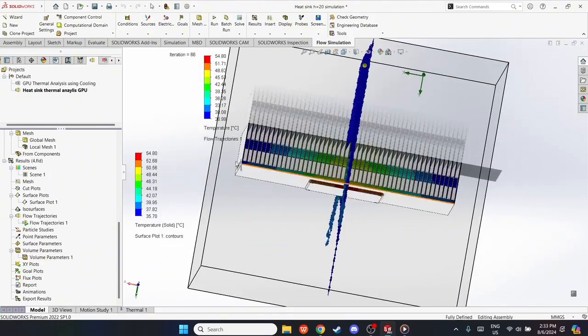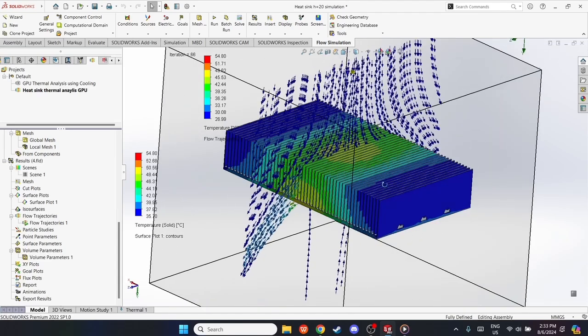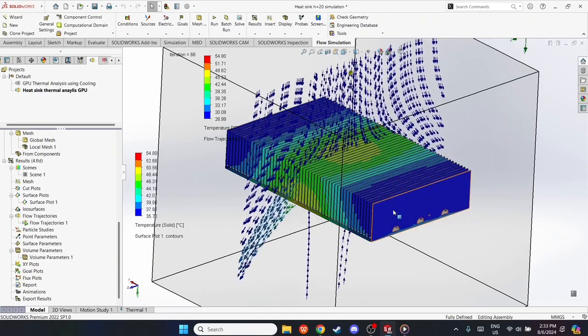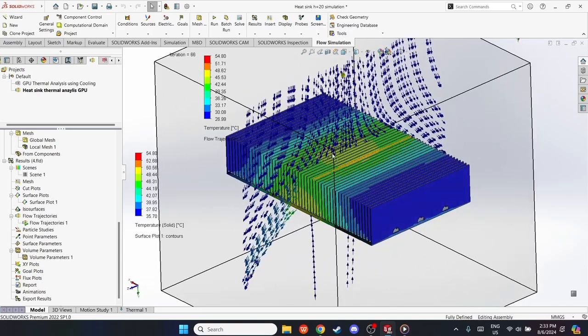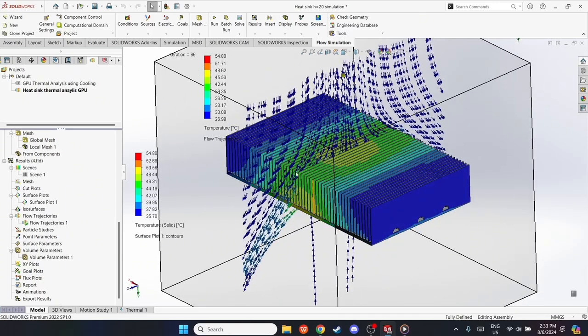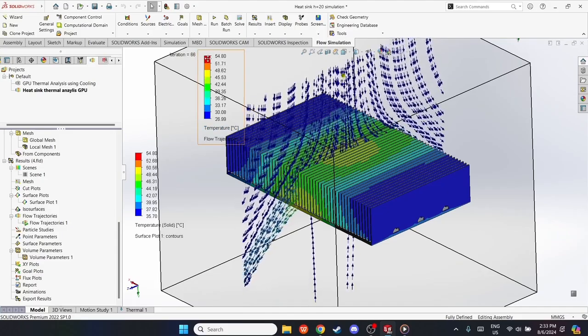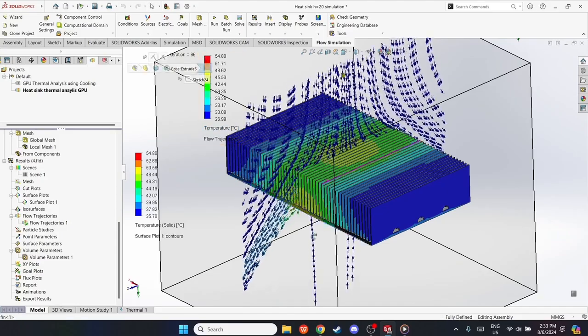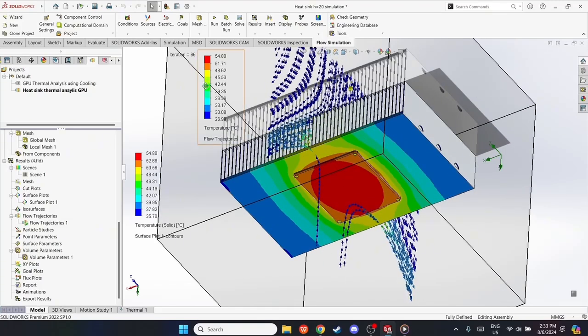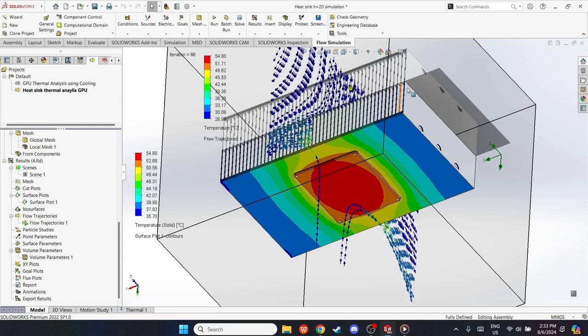Due to the massive size of the heatsink, the temperature at the very side of the fin is much lower compared to the middle part. The color gradient changes from red, being very hot, to blue, being very cold, while the green gradient outlines the mid temperature, which ranges from 39.35 to 45.